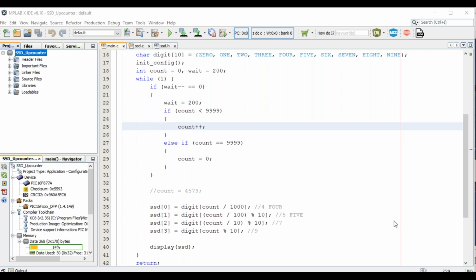How to reduce flicker? You have to give the proper delay. Flickering in the sense, are you not able to constantly see? That may be because you have increased the delay. So reduce the delay, the flickering has to stop.